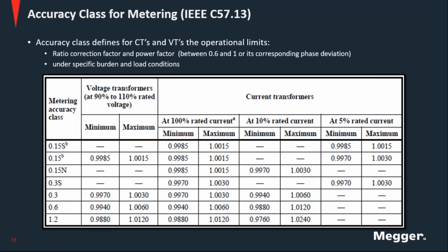So you have relays, you have coils, you have meters connected to these transformers, and well, it is providing signals, voltage or current, but of course it needs to provide some power to these elements. So the loading conditions must not exceed certain limits. So right now we're focusing on the accuracy class, and later on we'll talk about burden.